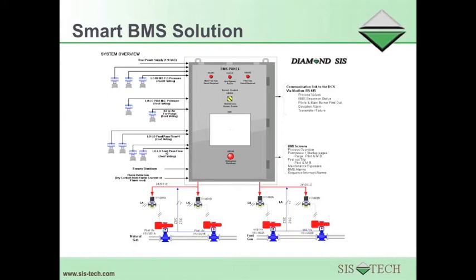The maintenance bypass key switches are replaced by one bypass-enabled switch. This switch provides the permissive to set the software maintenance bypass per each function. HMI with permissive pages, process overview, diagnostics, maintenance bypasses, and alarms.